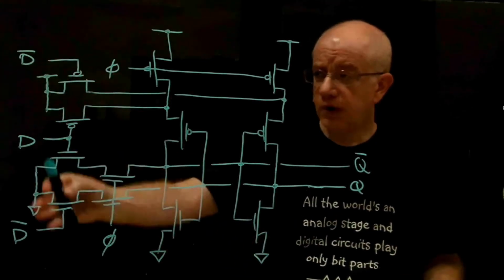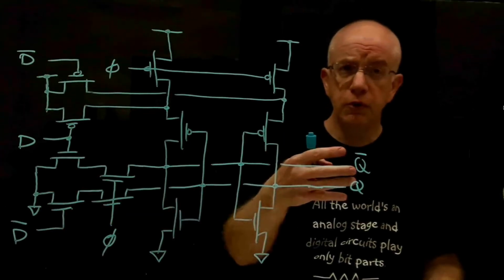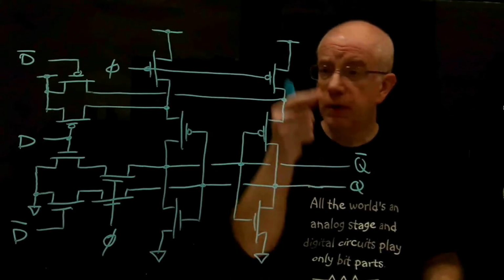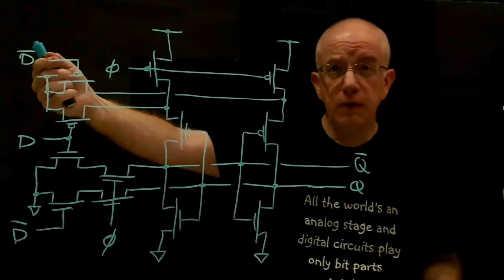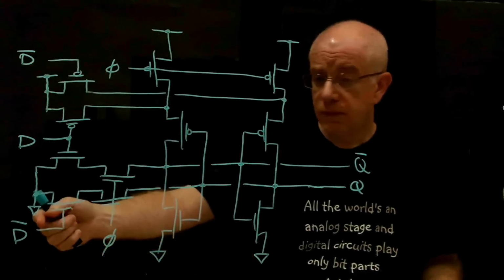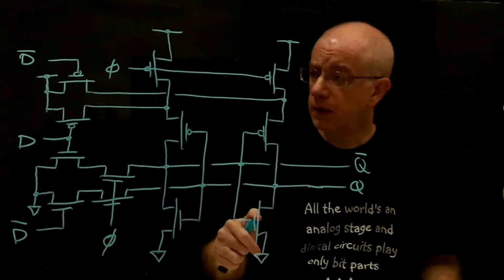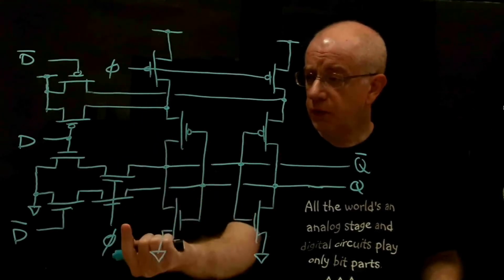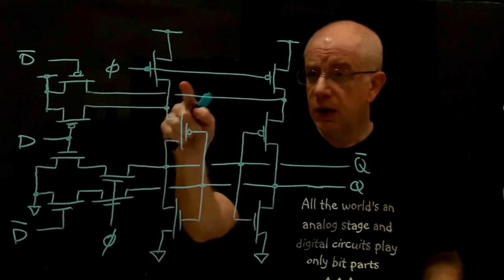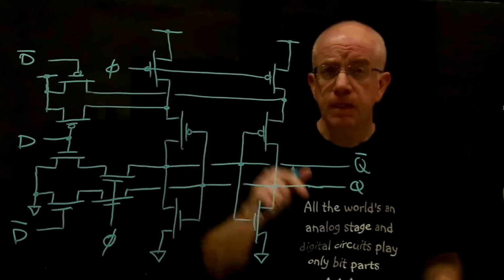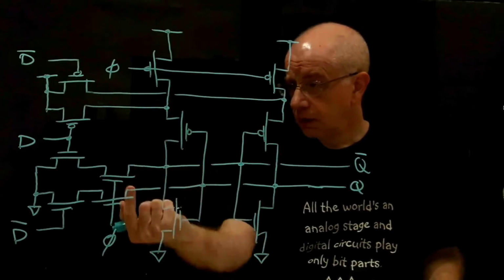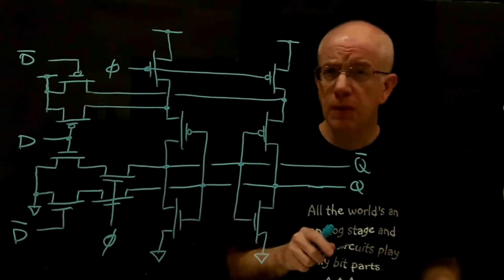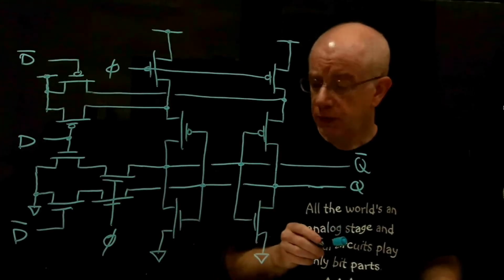We've got all the D inputs coming in from the left-hand side. The Q and the Q bar outputs are available on the right-hand side. And presumably we could line up the Q bar where it has to go in to feed into the D bar of the next stage, and also fork that down here. Now we have this clock strip of poly we could imagine going up here. And it would be nice if these two transistors could somehow be vertically aligned with these two clock transistors here. So now how might we think about doing something like that?